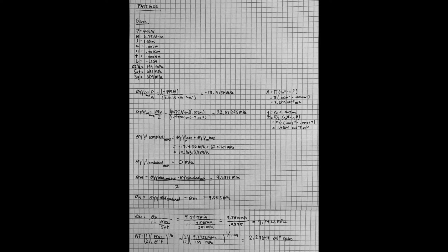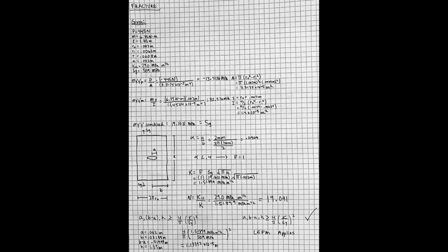We can justify these equations because in our fatigue model, we use the modified Goodman approach, which is reasonable for brittle materials and conservative for ductile materials. We also calculated sigma AR for fully reversible stress and used this in our SN relationship. In our fracture, we made sure that LEFM is met, and so that was an appropriate model to use for our fracture failure.